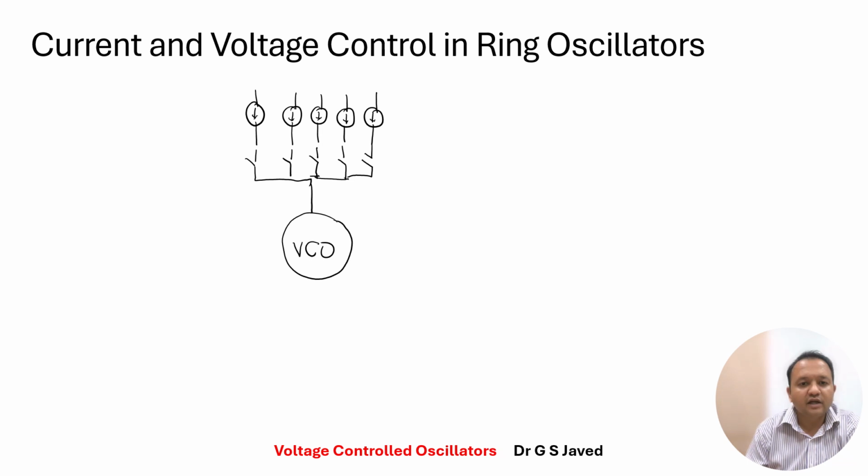And the way the connection is going to be given is the center line will have the always on current source. That means you will have the smallest value present over here, which we will call current as I. Then we will keep the next nearest one to be another I, such that we can have 2I current source, and the adjacent one will be 2I.